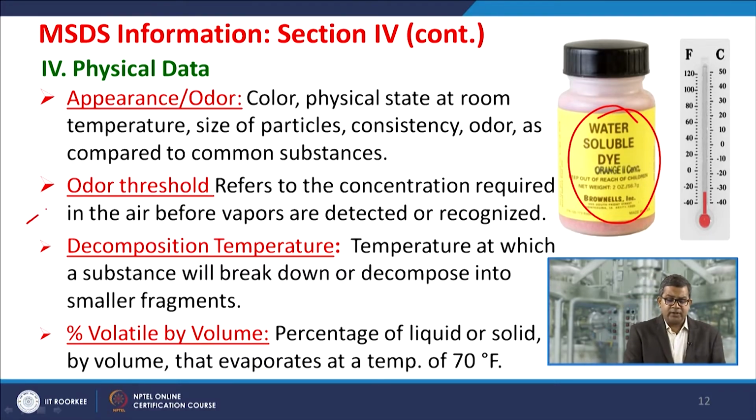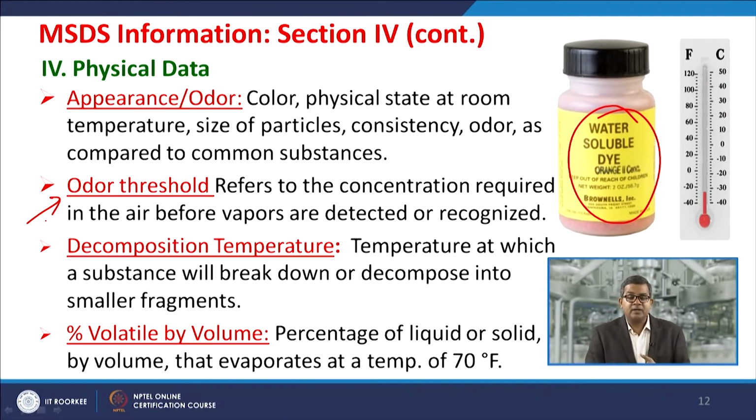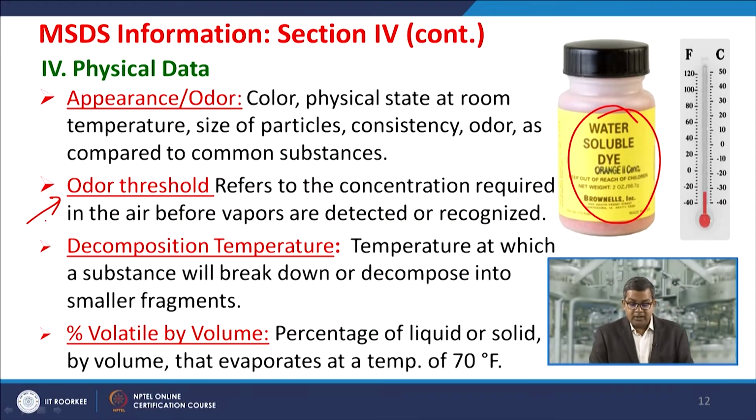Now this is again very crucial because you must know or you must experience all these odor thresholds so that you can recognize that this is present at your workplace and this is beyond the threshold limit value. Then decomposition temperature, because sometimes if temperature rises by any means, then some component may get decomposed and sometimes they may create a problem at the workplace. So you must know what my decomposition temperature is, the temperature at which a substance breaks down or decomposes into small fragments, and these small fragments sometimes may be dangerous.